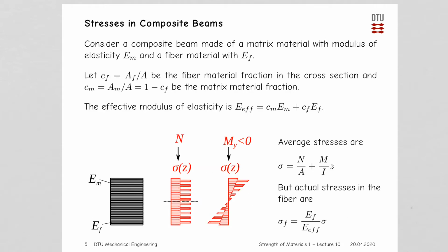One last point when we talk about composite beams, the last case here with the uniformly dispersed fibers, is that it is very important to have an assessment of the stresses in the fibers or the stresses in the material. So let's have a slightly more detailed look at the stresses in the composite beams. Having computed our effective Young's modulus with this very simple formula dictated by the volume fractions, when we then find our moment and our normal force, we can compute the stresses in our composite beam.